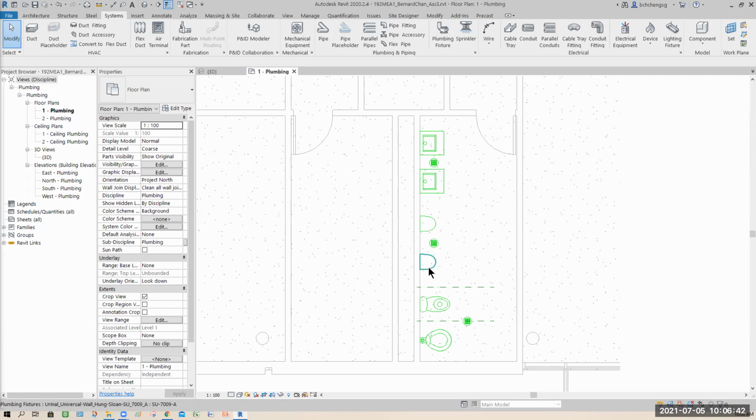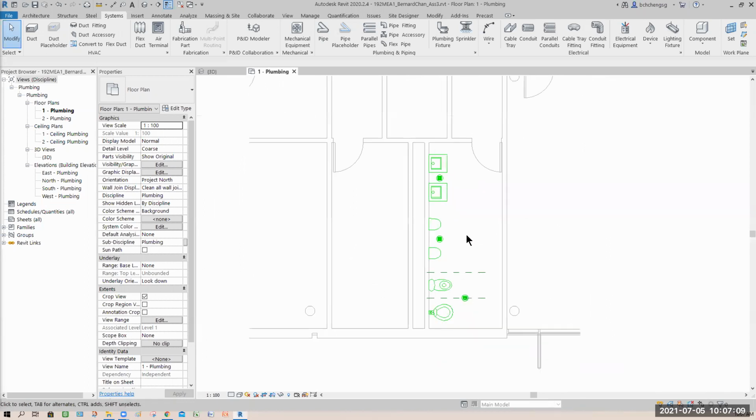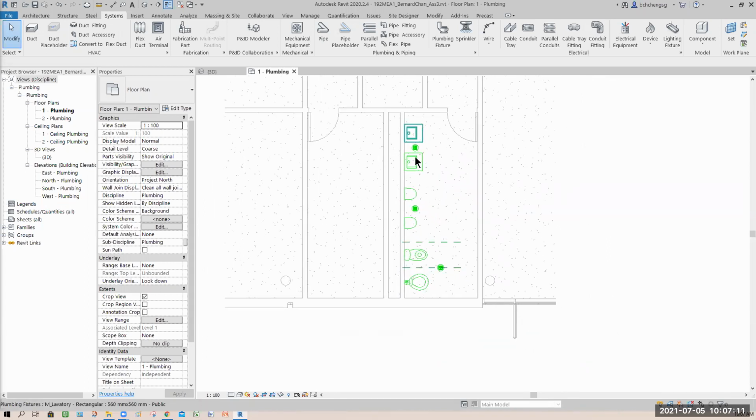But of course, sometimes when components are shared, the color will change. As you guys know, your aircon, the AHU is shared with the exhaust, sorry, the return and supply. That's why it's black color. If not, it's magenta and blue. So all this you got to understand. So we created the piping system. So have you all done that?